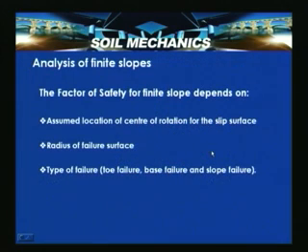In the analysis of finite slopes, the factor of safety for a finite slope depends on the assumed location of the center of rotation for the slip surface, the radius of the failure surface, and the type of failure, whether it is a toe failure, base failure or slope failure.